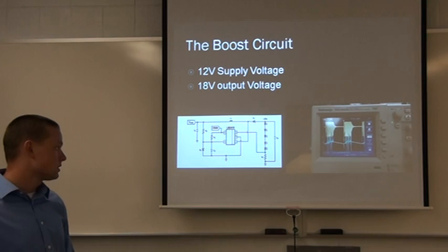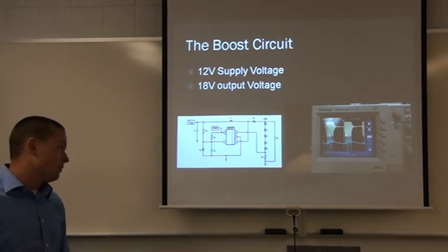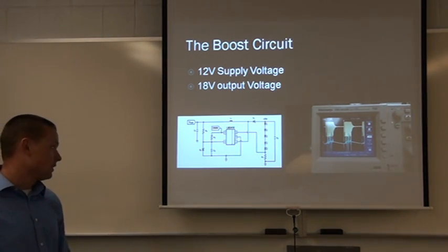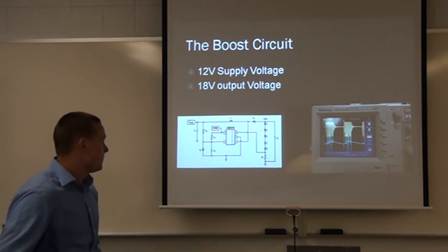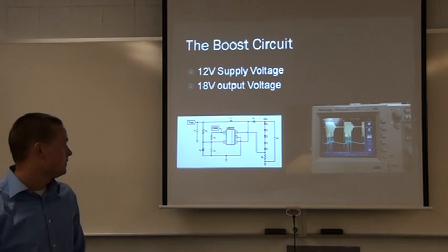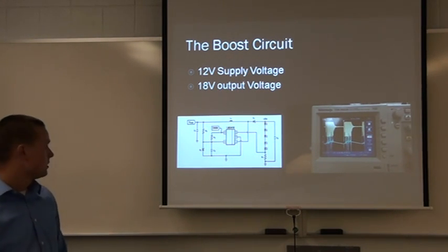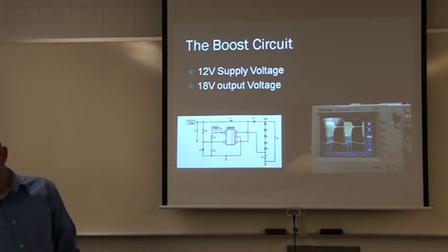The lower graph, the blue one, is the output on the capacitor that is charging up to 190 millivolts. And then it just slowly rides back down until it needs to be hit back up to 190 millivolts, and that voltage is running back to the feedback pin of the chip, pin 3. The dimming is controlled at pin 4.